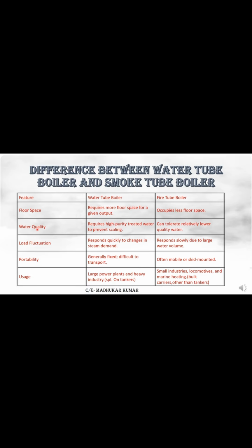Water quality. See, the water tube boiler needs high purity treated water to prevent scaling. Because in tankers, basically, every day you have to do the boiler water testing and the required chemicals have to be added. But in the case of the fire tube boiler, you have tolerance because of the large quantity of water and the pressure is also not very high, so weekly also you can do it.